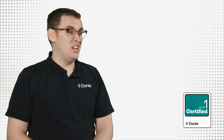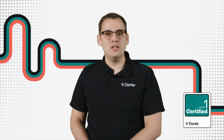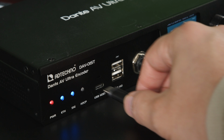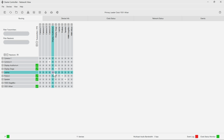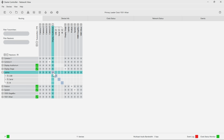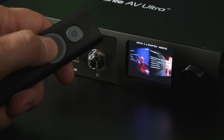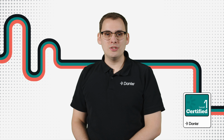A little stressful, right? But then, you spot a decoder right next to you on the stage, connected to the big screen. Here's the trick. We plug the USB receiver for the clicker into the decoder. Then, connect a USB-C cable from the encoder's USB host port to the computer. Finally, make the subscription in Dante Controller from the decoder to the encoder. Just like that, when you press the clicker, you're controlling the slides. Great, right? This could be a clicker or a mouse or a keyboard.